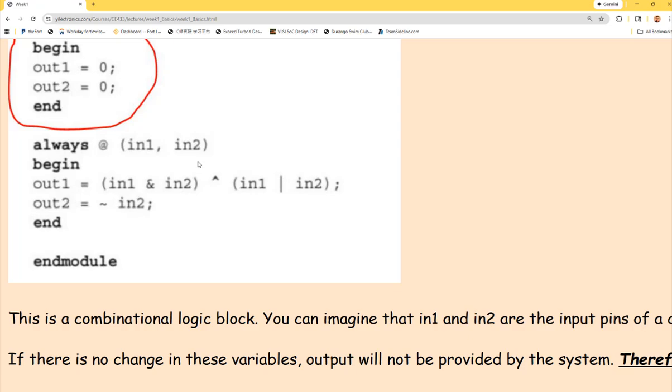But for the sequential design in the future, we are putting the rising edge or falling edge of the clocks in there. So that means it's actually being executed forever, because whenever that input on the sensitivity list gets updated, it updates all the hardware's output. That's the way it's being executed forever. It's always updating the output of the hardware, the piece of hardware, instead of running the instructions from the instruction memory from top to bottom as a loop. Okay? That makes sense, right? It's just a piece of hardware.